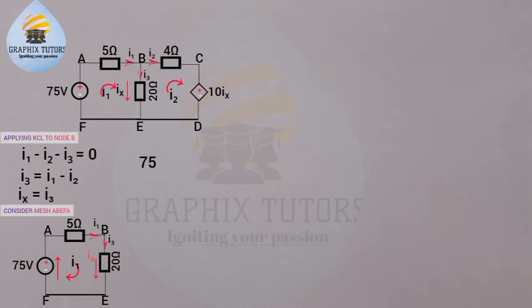Now when current flows through a resistor in the same direction as my own direction, I am going in this direction and the current is also going in this direction, we'll have a negative voltage. So we'll have 5 times I1, that will give us minus 5I1, because we are going in the same direction as the current.